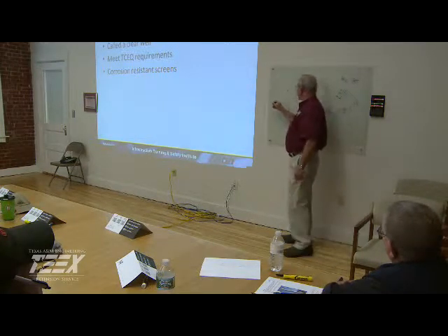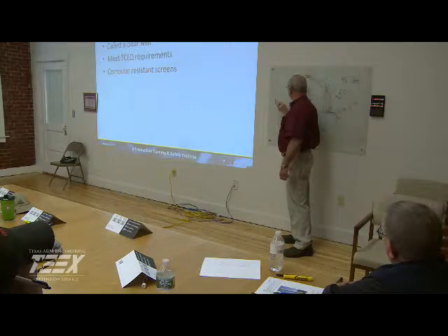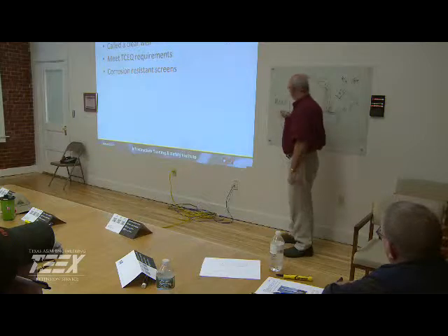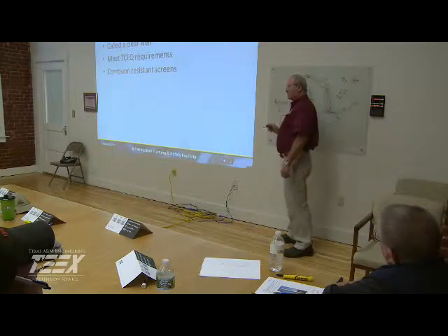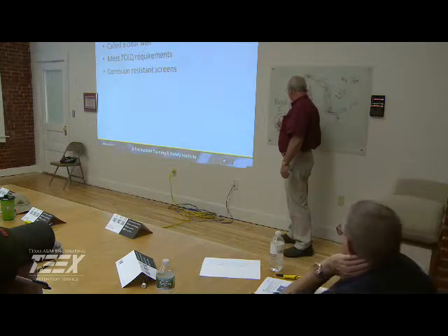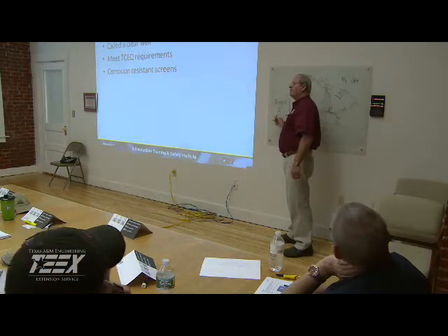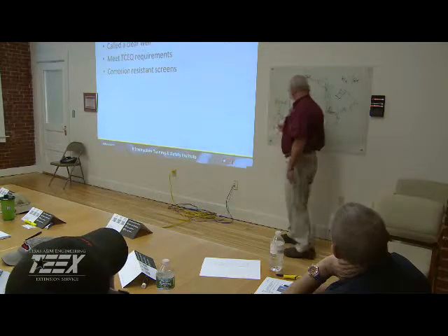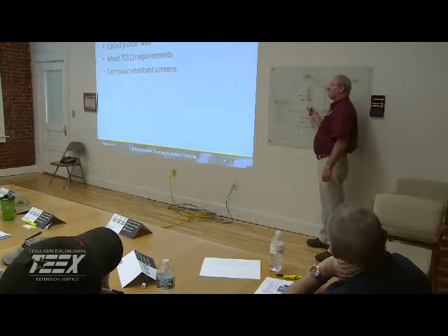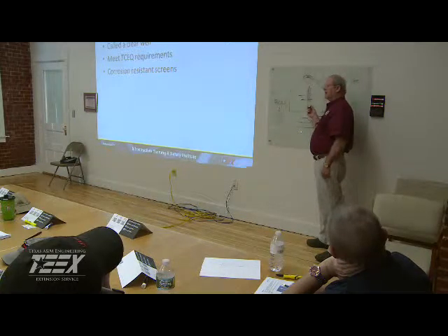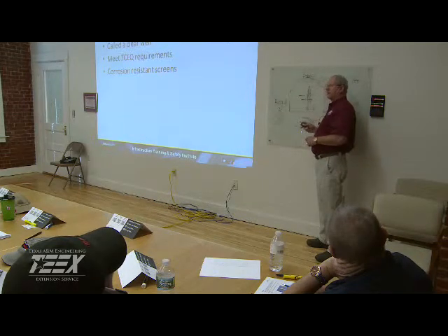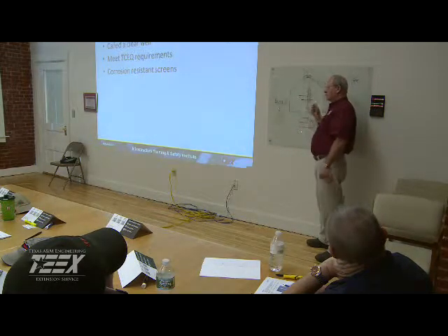Now, on your tank, some facilities are required to have a gauge. The gauge is a head gauge. Believe it or not, they'd rather have it in head than in PSI. And it should be in 2-foot increments, and the minimum diameter is 3 inches. Okay? And the numbers should be visible as best possible again. So if I have a gauge over here, I can see it from the road again. Okay? If I have an access road driving up to the tank, I can look in there with maybe a pair of binoculars and see that gauge.